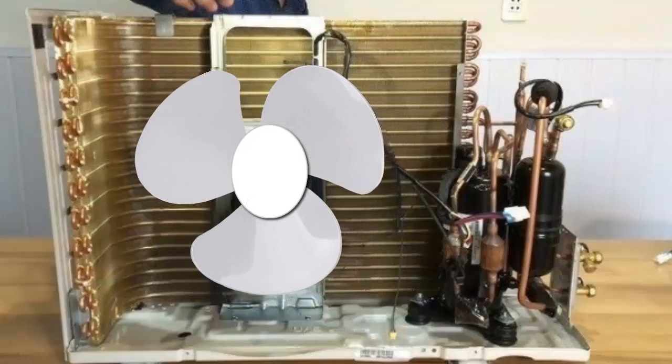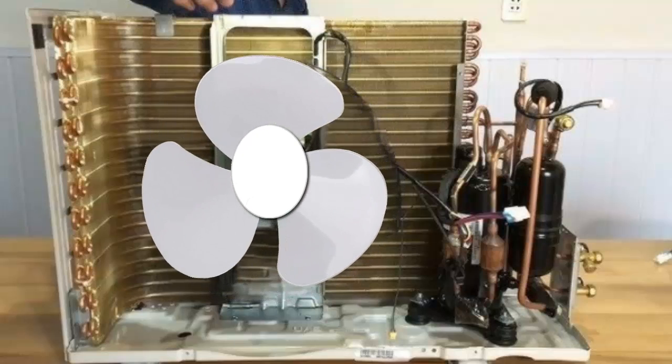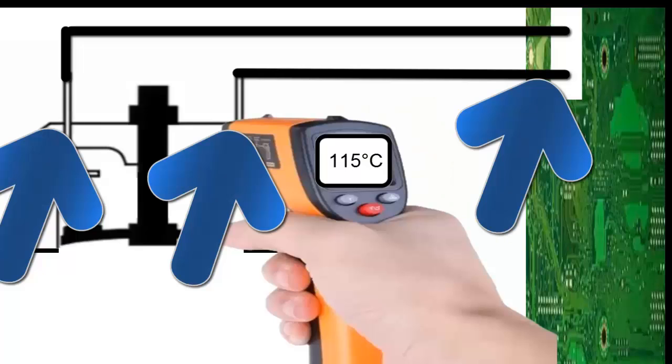3. Visually inspect the normal rotation of the outdoor unit fan and the cleanliness of the condensing unit. 4. Inside the outdoor condensing unit, check the compressor thermostat cable. Ensure that the cable is correctly connected to the outdoor unit connector. Also, check all possible connections.